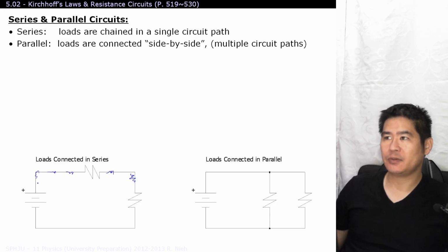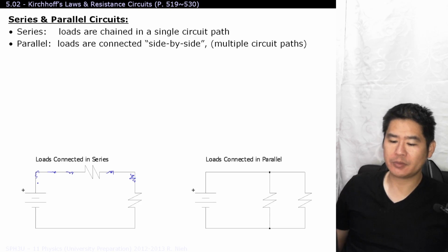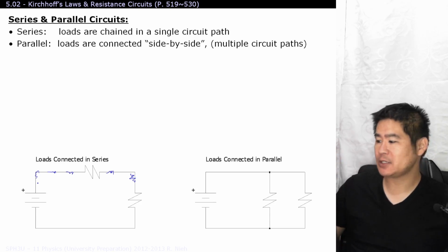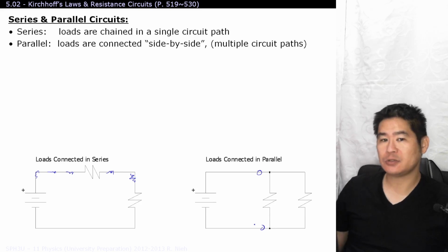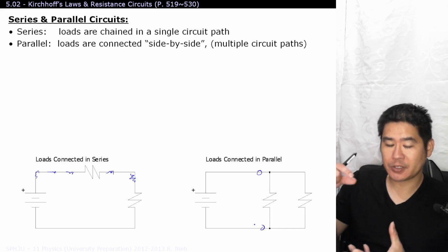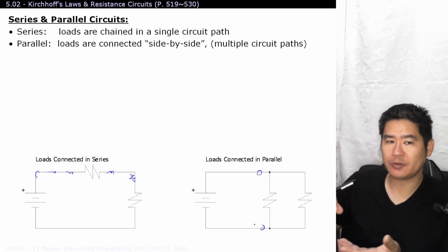On the other hand, with regards to your power bar that you plug things in, you want to be able to readily plug things in and unplug them when you don't need them anymore. In that case, you're just connecting to the two rails of the mains. And you're just plugging everything in parallel. So every device that's plugged into your power bar gets 120 volts. It's not shared.